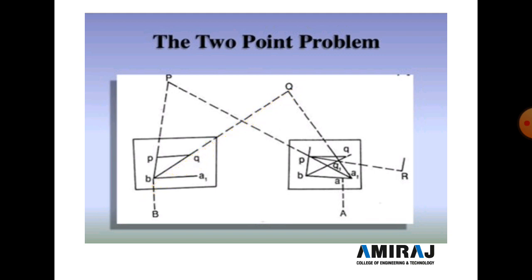The distances are measured by the measuring tape. BQ, BP and BA, three lines, are drawn using the scale, which was already discussed in the last slide. Now all the setup is transferred to point A, and from point A bisect the P point and the Q point.